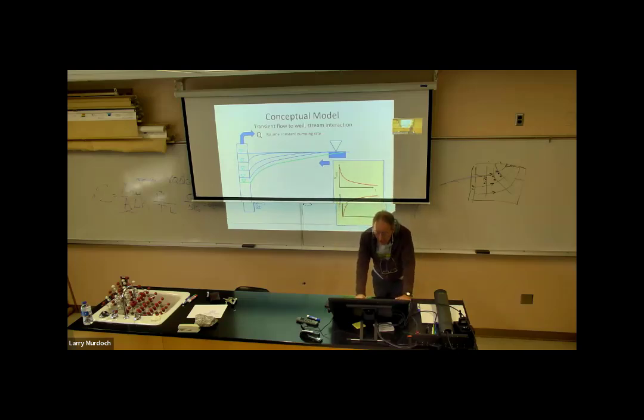Okay, so that means that we no longer have to have more drawdown with time to progressively release more water from storage. We can get it released from the stream. So that causes the head to flatten out like that, and the drawdown to flatten, and that allows us to go to steady state. So interacting with the stream is a way that wells can go to steady state.